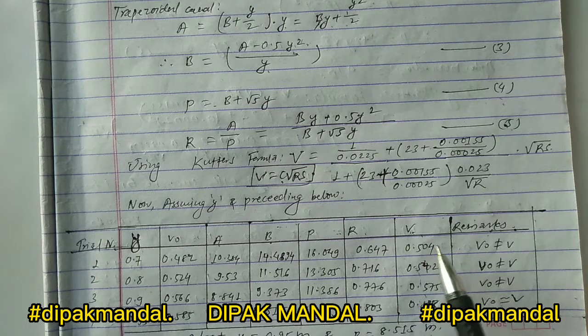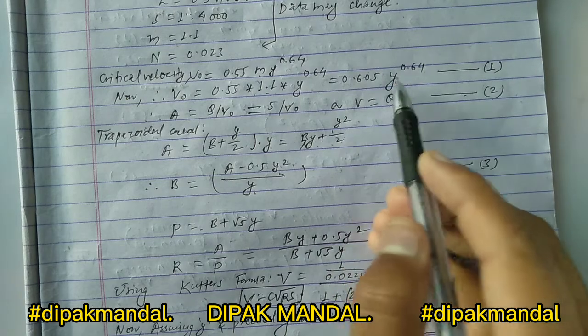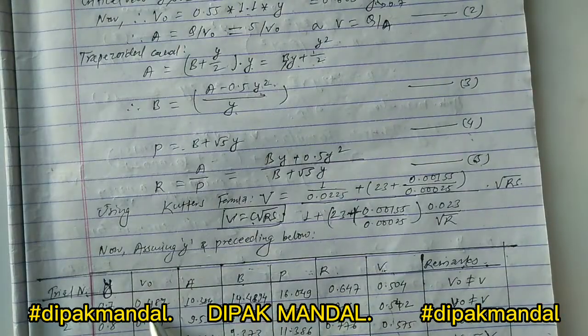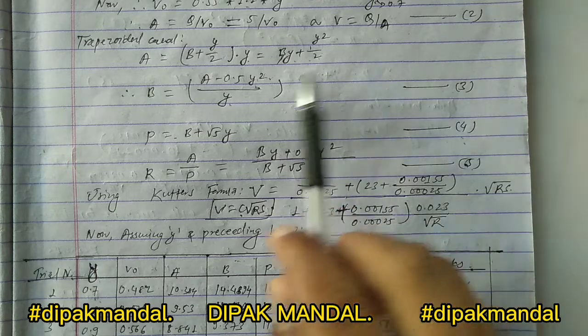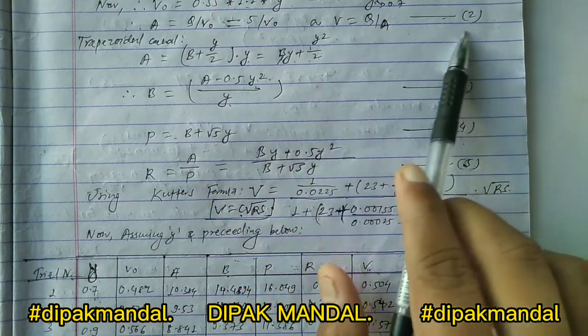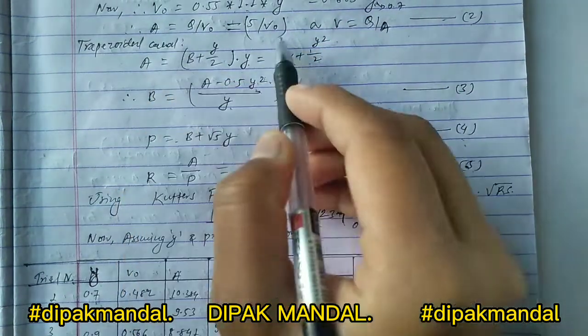Okay, so let's see. In the very first trial, the value of y is 0.7. Okay, whenever we take the value of y equal to 0.7, then we can calculate the value of v naught with the help of equation number 1. We put the value of y equal to 0.7, then we get the value of v naught equal to 0.482. Okay, then we have to calculate the value of A with the help of equation number 2. This is the equation of A equal to Q by v naught. Okay, A equal to Q by v naught.